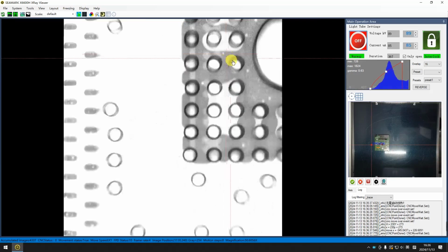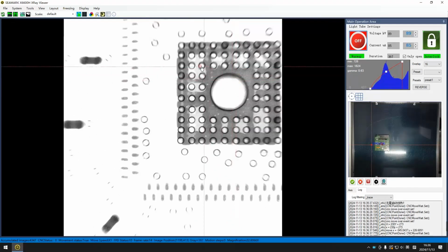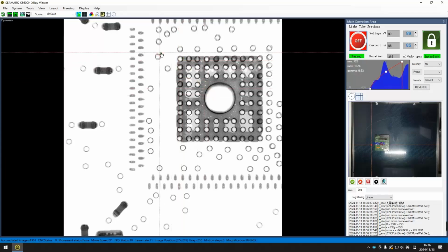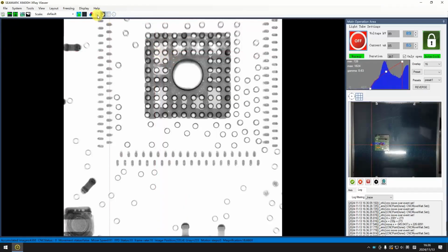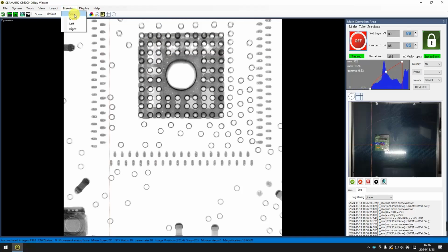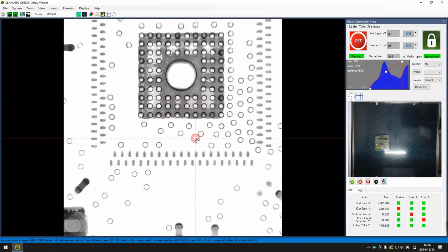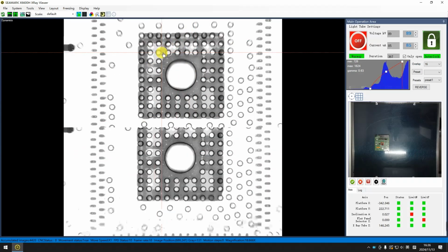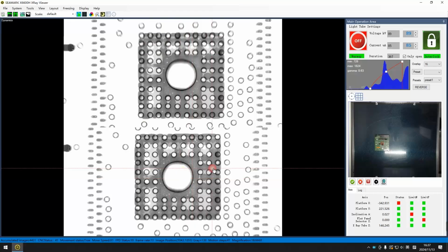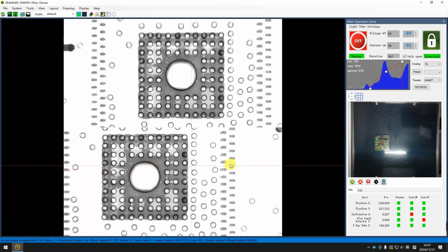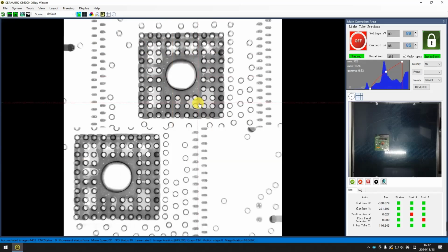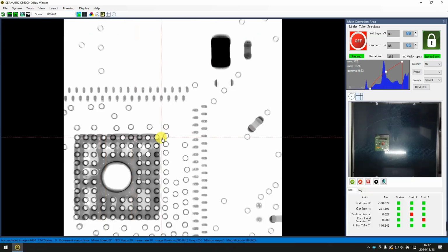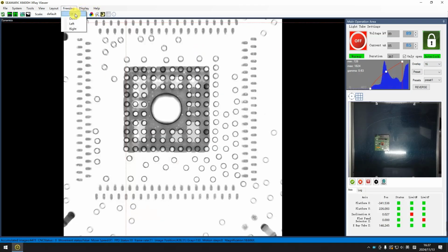And here I need to introduce a very useful function, the freezing. For now, I zoom out the sample and move it to the top place. You can see now I freeze the top side, and only the bottom side I can move. So we can put the standard piece on the top or the bottom or the left or right, and use another piece of the image to do the comparison. You see, this is very useful. If you want to restore the image, you can click the button again. You see, now I restore the image.